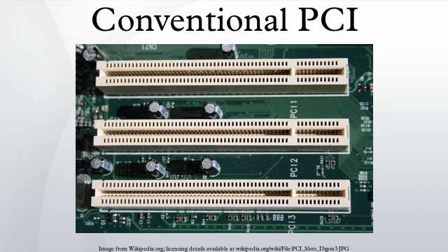The data recipient must latch the AD bus each cycle until it sees both IRDY and TRDY asserted, which marks the end of the current data phase and indicates that the just latched data is the word to be transferred. To maintain full burst speed, the data sender then has half a clock cycle after seeing both IRDY and TRDY asserted to drive the next word onto the AD bus.